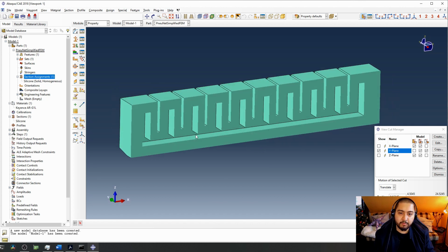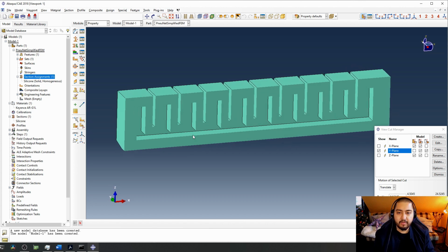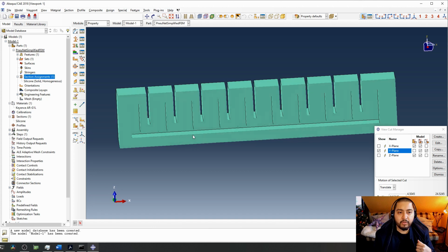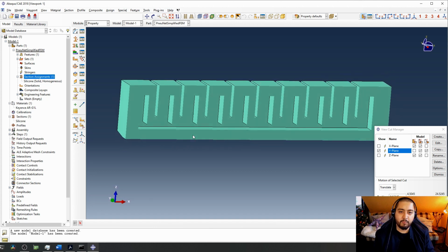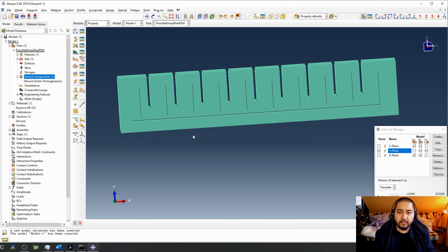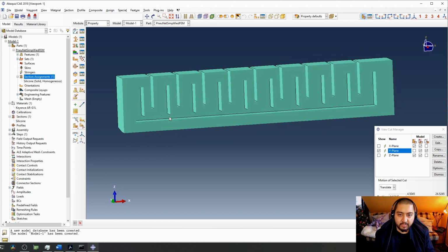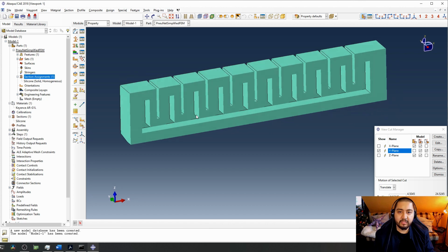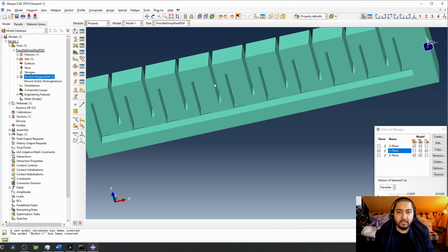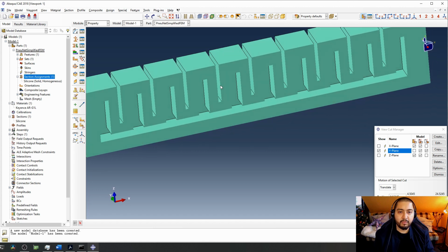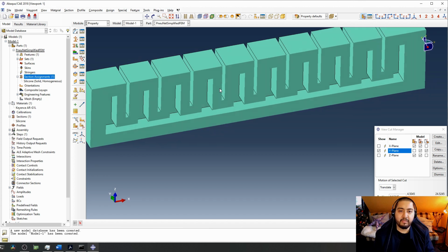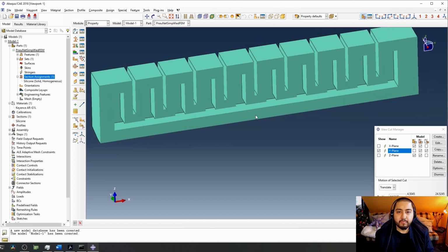We change them here, and as you can see, these are the inner cavities of the pneumatic actuator. So these are the surfaces on which we are going to apply the pressure, or on which the pressure is applied when you fill it with a fluid. In this case, usually we use air in the soft robotics research field. So these are the important surfaces, the ones inside. And other important surfaces are probably these outer walls, because they are going to be the ones mainly expanded after the pressure is applied.